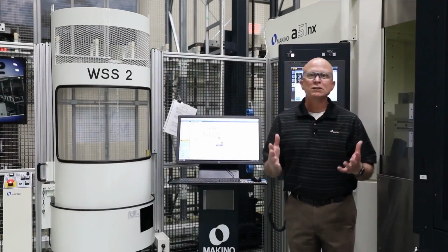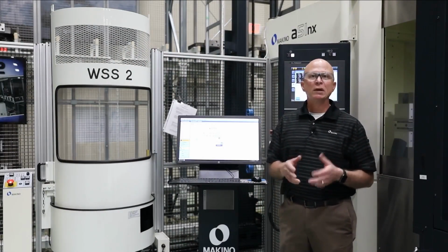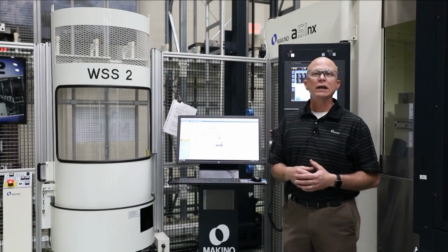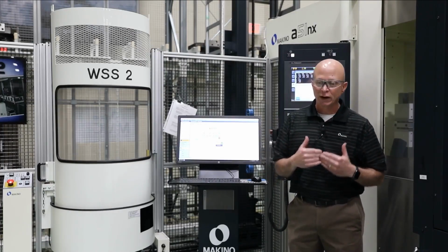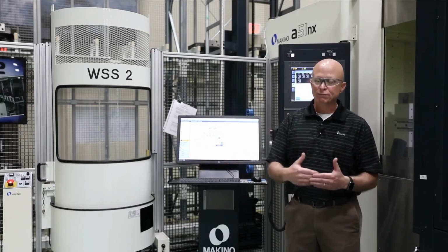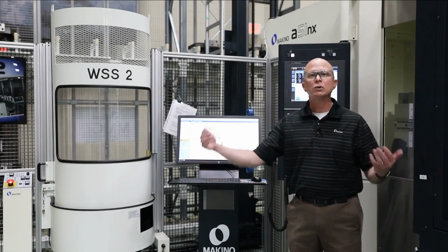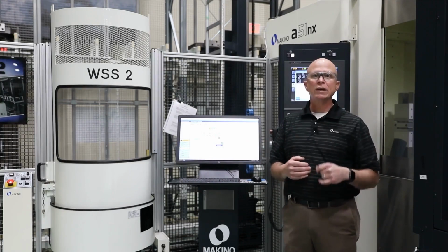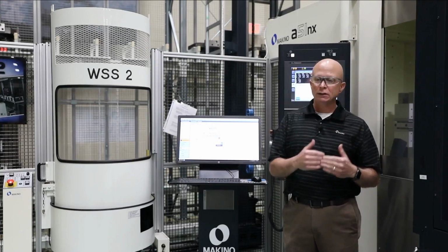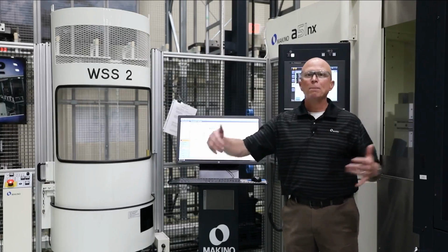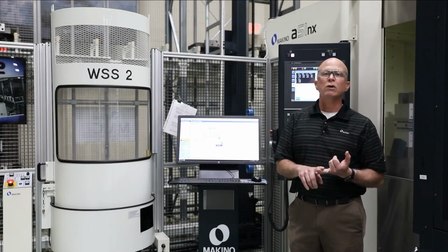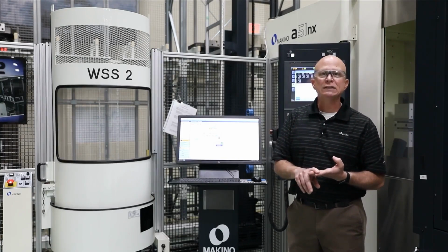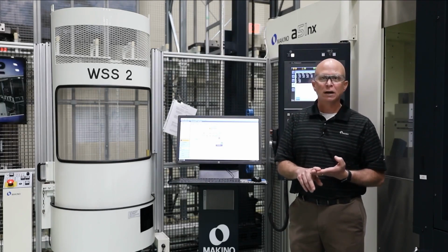So this demonstration, we're going to show that powerful Makino M code. That's that M319. So if you remember, M319 takes a very serial process, actually 4 different things, and moves them into a parallel process. So you're saving a lot of time by taking those individual tasks and putting them on top of each other. So it's going to stop the spindle, it's going to orient the spindle, it's going to stop the coolant, and open the ATC shutter door all at the same time.